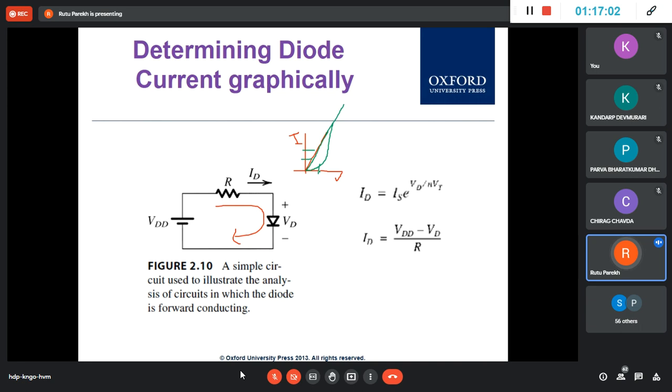If V1 is some voltage, then for the diode I will get this current, and if V1 is the voltage for R, I will get this current. So the value of current is different for the same voltage V1. Yes, ma'am. But that different value cannot flow here, because they are both in series. You understand my point, that the same current should flow. The same current should satisfy both the equations. Yes, ma'am. It is unstable and not possible; that's not how nature works.